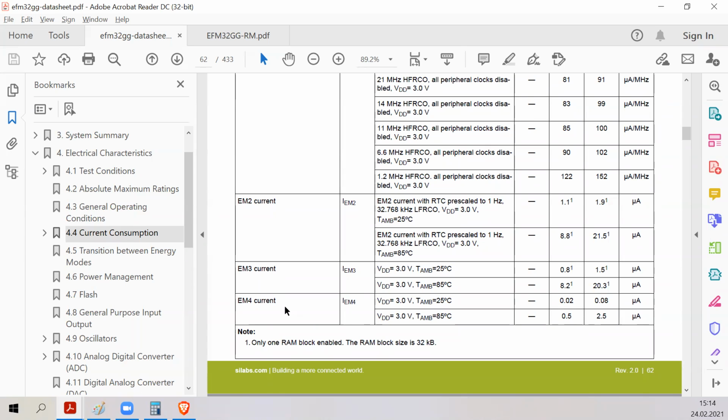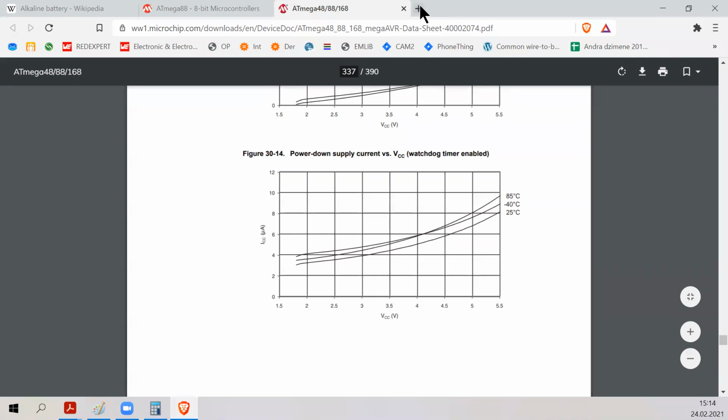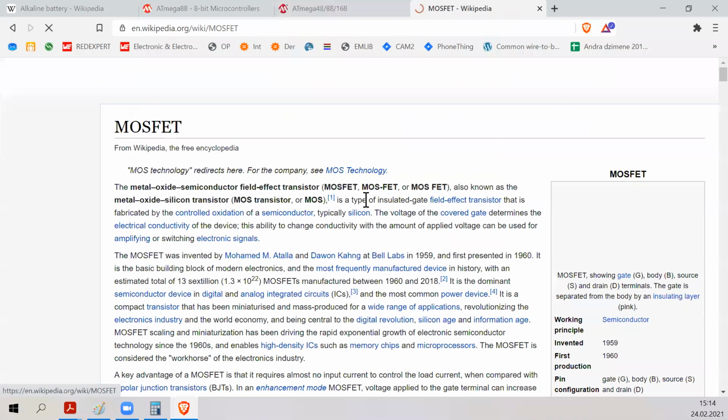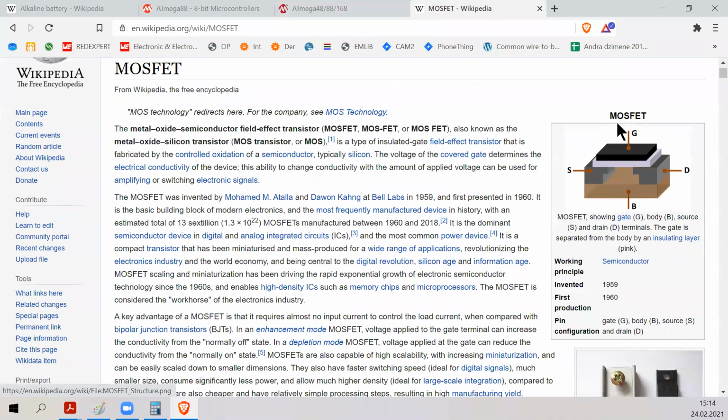So smaller transistor means that you can run it more quickly, and it consumes less energy, and it heats up less. So you would think it's better. But because it's smaller, its drain and source are located closer together. If it's smaller, the source and drain are located much closer together, so the leakage current is higher.